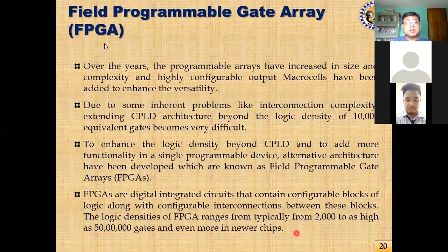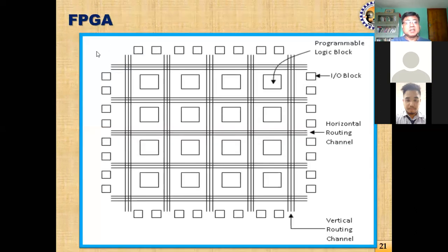So you see the architecture of FPGA is like this. In case of CPLD, if we compare with FPGA, inside CPLD we have got a certain number of PLDs. These PLDs can implement a certain amount of logic functions or Boolean expressions within it. But in case of FPGA, we will see only a small block, because this block can implement a very small logic function. This logic function I can describe as programmable logic block.